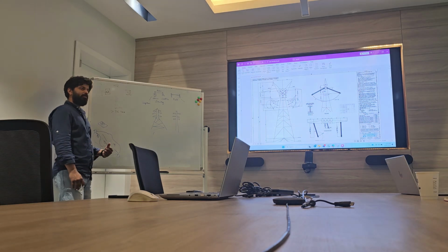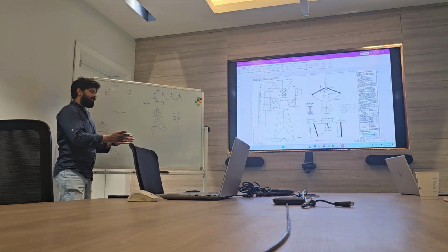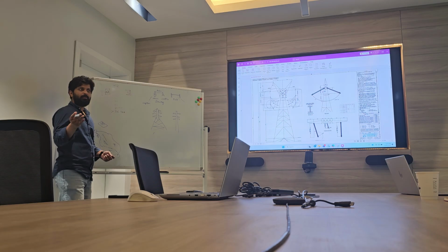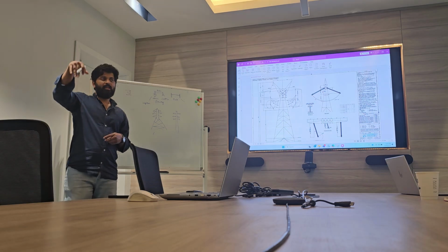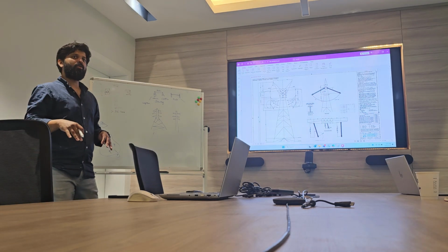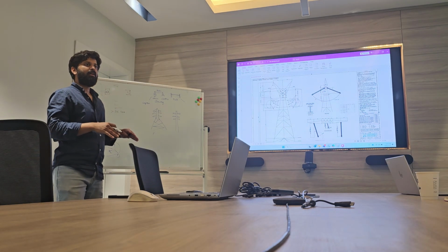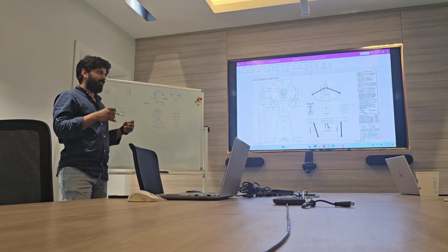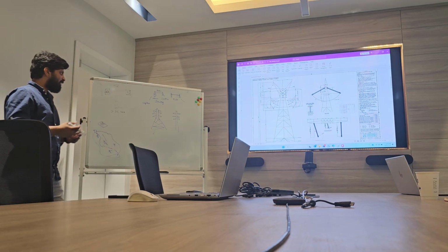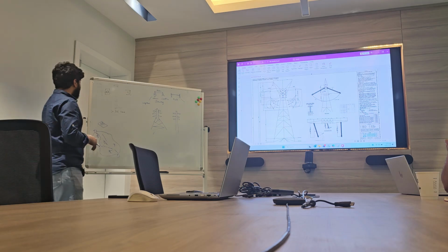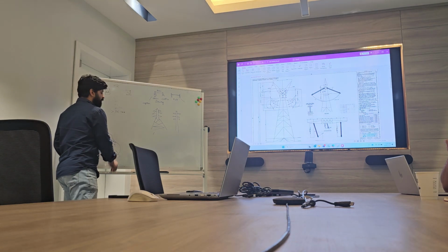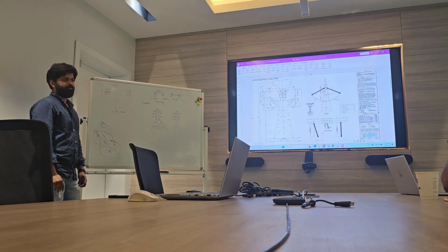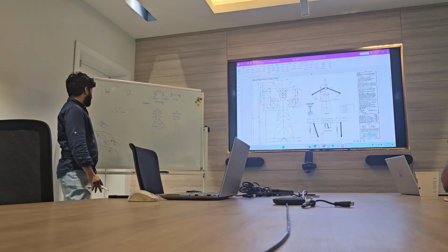You have to make an analysis before. If I buy this land, does it belong to anyone? What is the price of that land? If I purchase that land, how much do I have to pay? Then is there any hill, sand dune, river, valley, or wadi area where there is water? There are so many things. So based on that, we decide something called the ROW, the right of way.